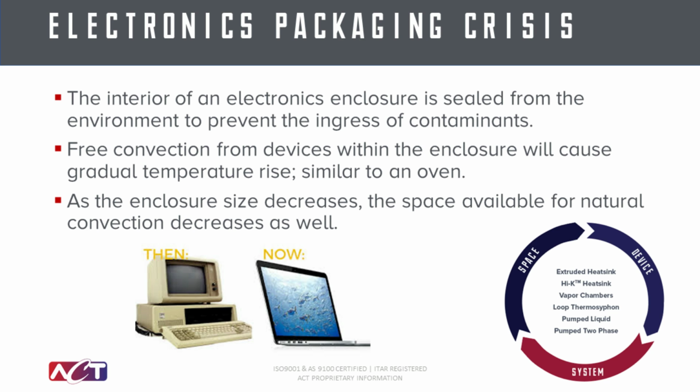Sealing these enclosures is a great way to do that, but it also seals them from the ambient air outside, creating an oven-type environment in which your electronics are going to continue to generate heat and continue to rise in temperature until they reach some steady state.